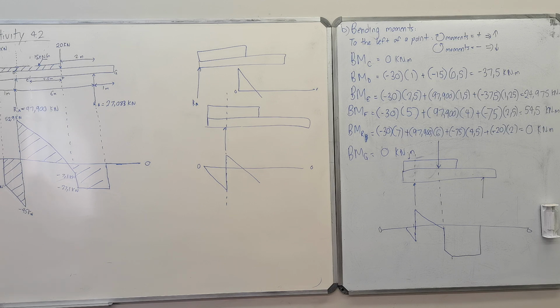Yeah, so mainly we're drawing a shearing force. Wherever there's a force, draw a line for it and divide it into sections. So like how I showed you here, this here would basically show that section. Here is basically the section here, and here is basically that section. Okay? For concentrated loads, it's a vertical line. For a distributed load, it's a slope. Okay. Then they want your bending moments.